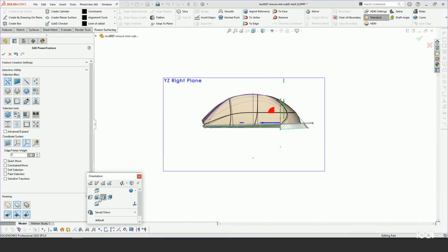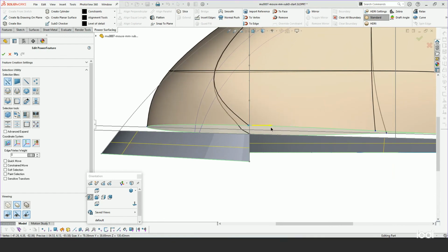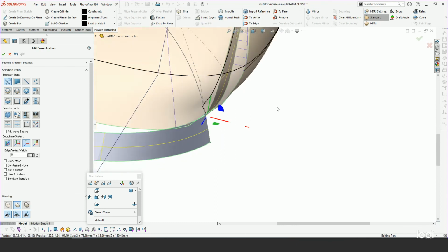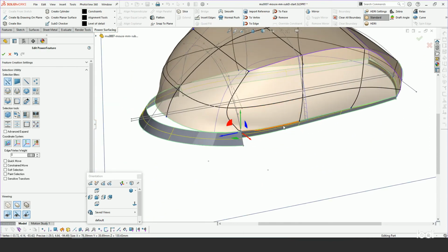You can see that I struggle with this also, even with using it as much as I have. So now that we've got it there, let's just do that again for that vertex. And once we have those vertices, let's go ahead and do a loop select, but let's not select the back ones. We're going to align those to a different reference right here. So what I've just done is loop select all these ones here, and I'm going to align it by edge to this imported reference.